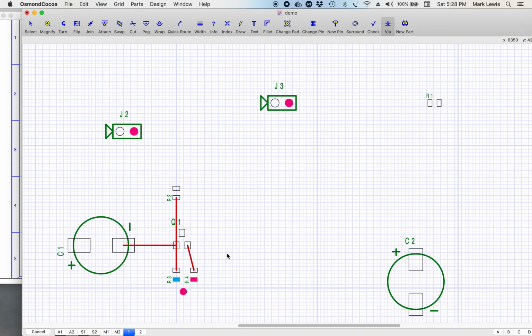And then what I'm going to do, well, let me explain the vias first. This is just a regular via, and you can have what's called a blind via. Let's say this board has 4 layers, 1, 2, 3, 4, and I want to make a via that only goes from layer 2 to layer 3. Doesn't pass through the whole circuit board. That's called a blind via. It's blind because you can't see the top of it and you can't see the bottom of it. It's blind to you. It's like invisible. Then you also have a filled via where the via is actually filled in with some material. Oh, I'm sorry. I made a mistake on that.